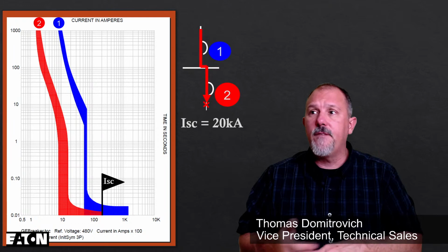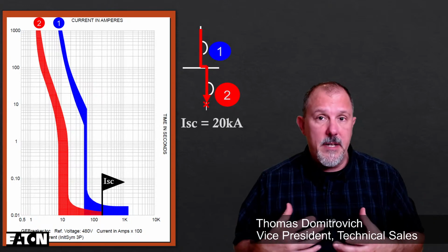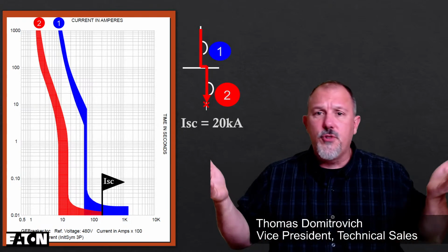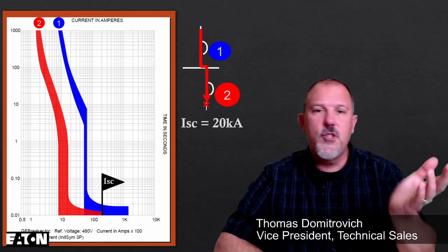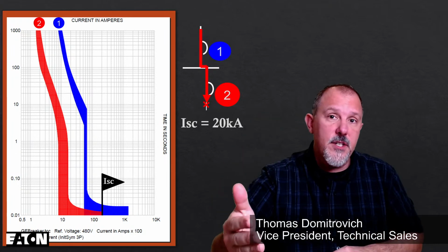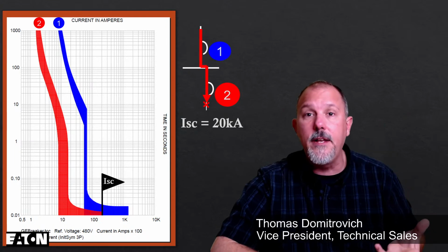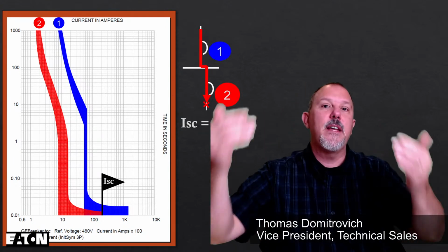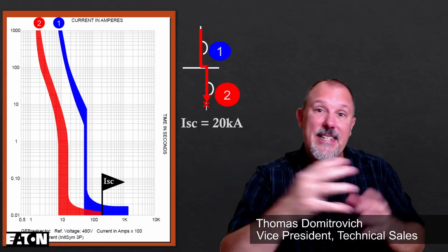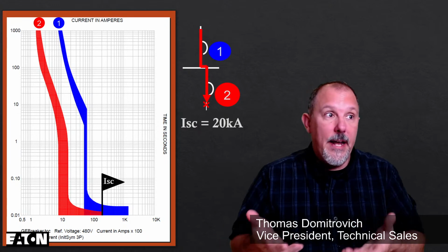Now, from a coordination perspective, I may say, you know what, I am more worried about equipment damage. My customer has cost considerations. I might pull 2 circuits to a load from 2 different sources and say, well, there's my redundancy. Now, if there's a problem on this circuit and it takes a cascading event, I have another circuit over here that I can turn on. The chances of both of those having the same condition to trip, I've addressed my reliability in a different way than selective coordination. Now, it'll cost me more money.